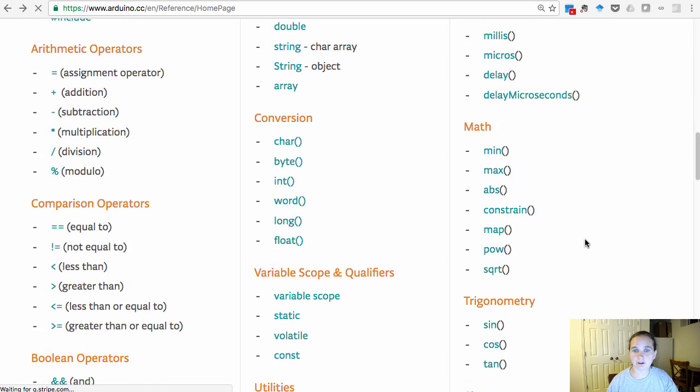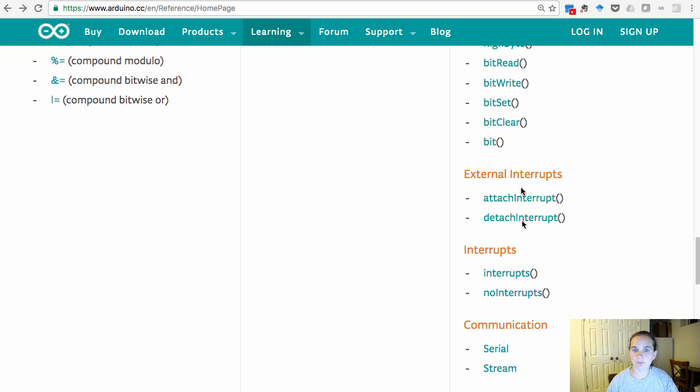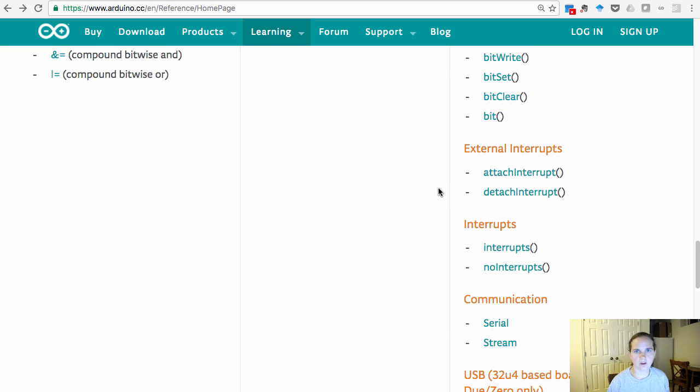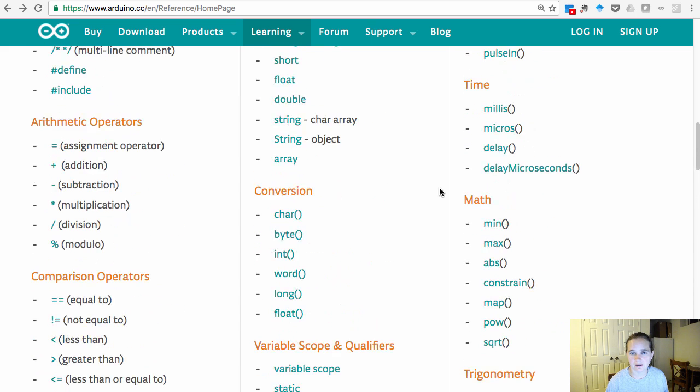And then finally, if I really want to get more complex and more interesting, as far as timers go, interrupts are a great way to do that. They effectively let me create a multi-threaded Arduino program. So I can be doing something else while I'm waiting for a timer to complete. One of the things that I'm interested in for a mechatronics system often is figuring out at what time certain things happen. And I might be interested in a sensor value, trying to understand my sensor data from that point of view.